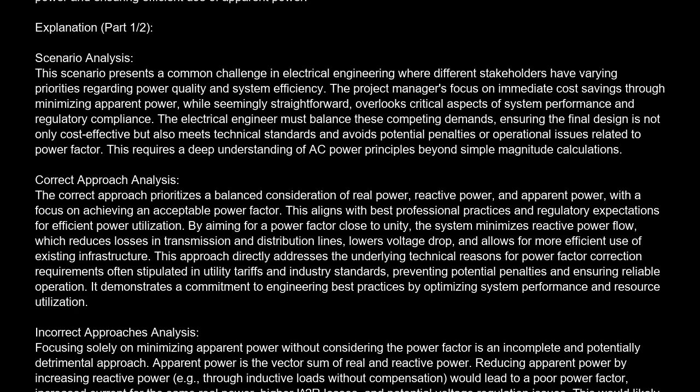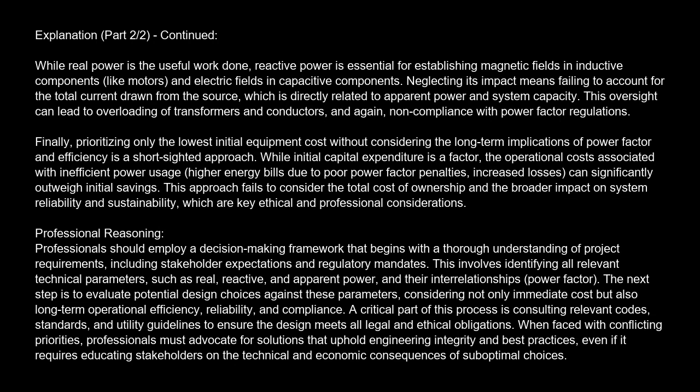Another incorrect approach would be to ignore reactive power entirely and only focus on real power. Real power is the useful work done. Reactive power is essential for establishing magnetic fields in inductive components, like motors, and electric fields in capacitive components. Neglecting its impact means failing to account for the total current drawn from the source, which is directly related to apparent power and system capacity. This oversight can lead to overloading of transformers and conductors, and again, non-compliance with power factor regulations.